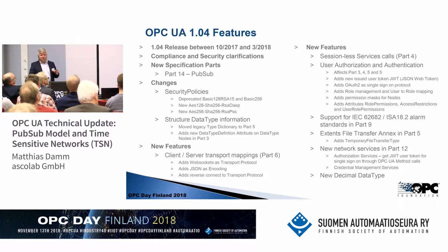A big chunk of work was also related to user management or user authentication. So in OPC UA, we always had standard tokens, like a way you send user information from a client to server, like username, password, certificates, anonymous. And one thing we added was like a new token type, but more important, we also defined the user authorization, so defining a mapping of users to roles, to expose roles in OPC UA servers, to manage roles through OPC UA, and also to manage permissions.